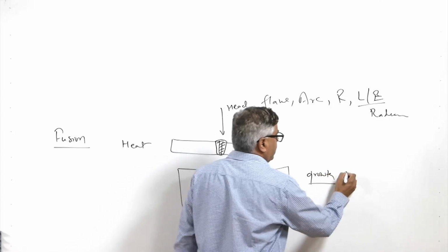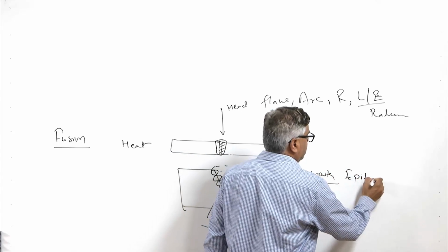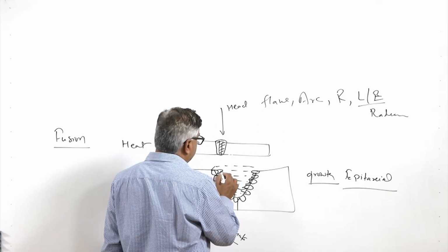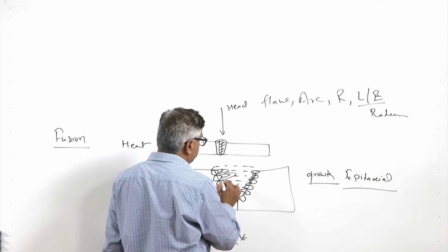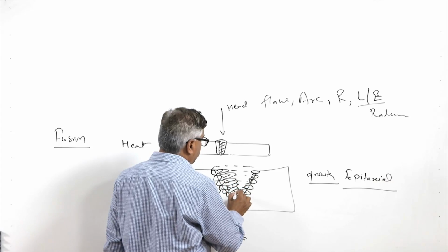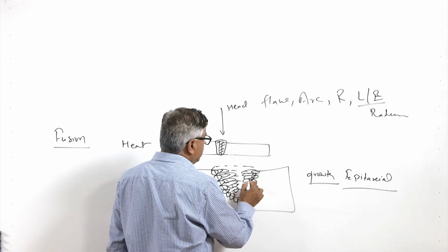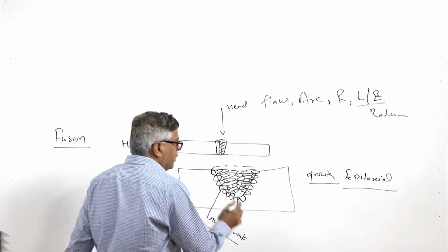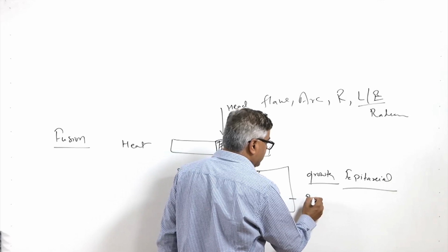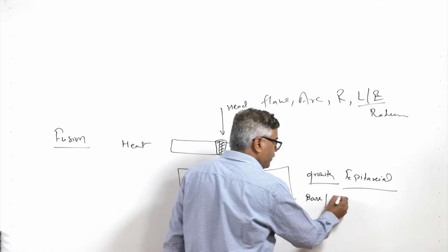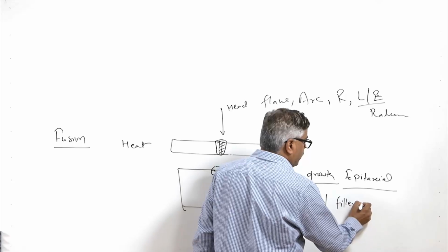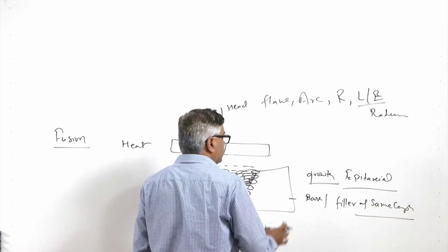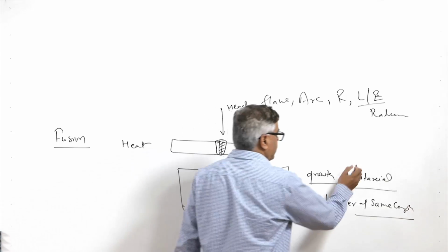This is called epitaxial solidification, and gradually the entire amount of molten metal is consumed by the growth of these grains during solidification. So, it does not involve the typical steps of nucleation and growth. In all those cases where just the base metal is melted, or even if a filler of the same composition is added, epitaxial solidification is observed.